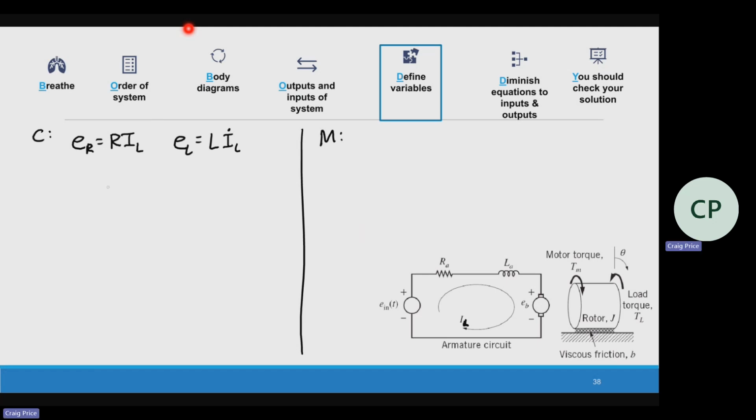We just wrote down the definition for back EMF voltage. Maybe we wrote it down. It is on the equation sheet, so if you didn't write it down, you don't have to memorize it. But what is that equation? Oh, I had a box on the slide. That's fine. It's on the equation sheet. It is the back EMF constant times theta dot. So the faster this thing spins, the more voltage we get out of it.